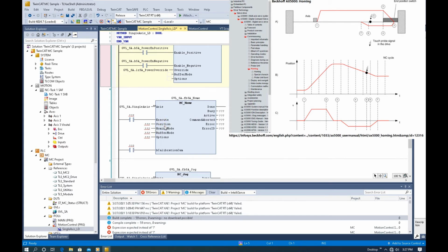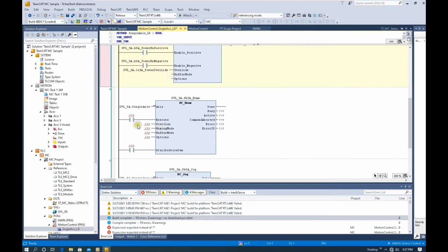In some cases, other than using the home sensor, we could also use the zero mark from the encoder, probably the zero mark from the sensor, and set the actual position. That will be very accurate. Whether to use the passive home or active home totally depends on your application. For example, in my project, in most cases I will use the passive home. That is because for positioning control, usually we will travel our pallet or mechanical parts to line up with the tooling.